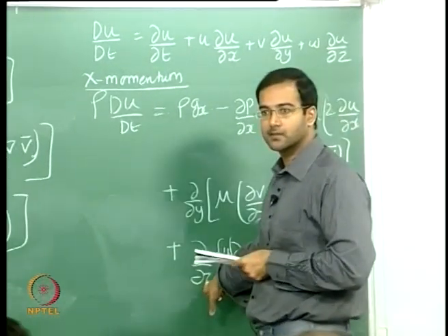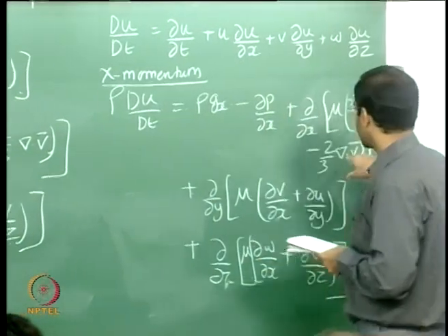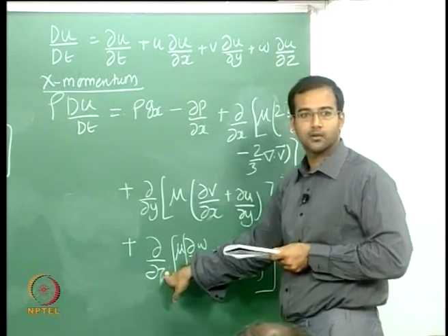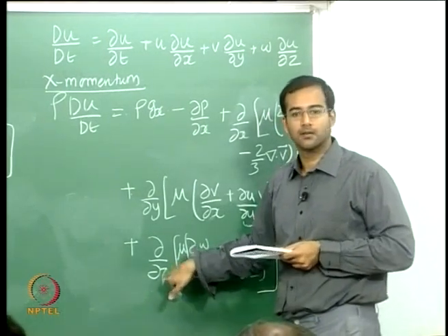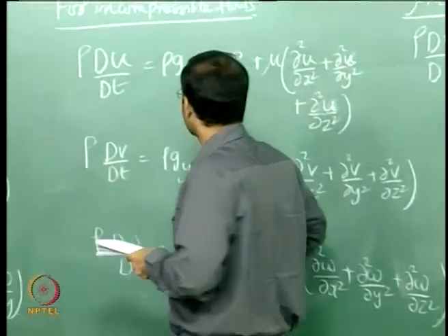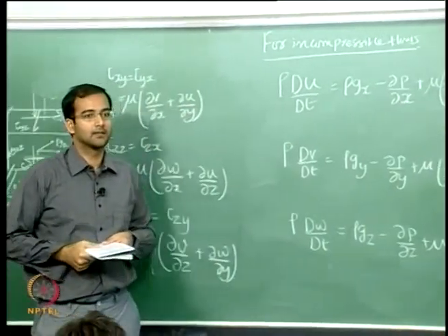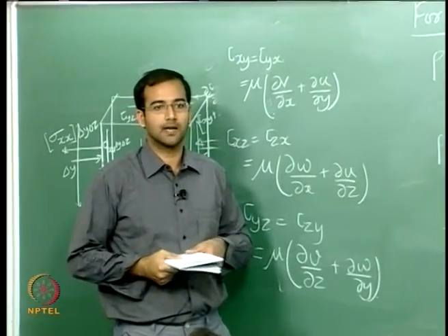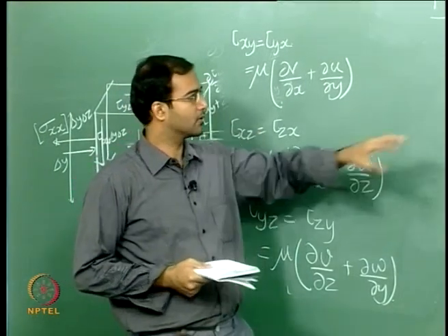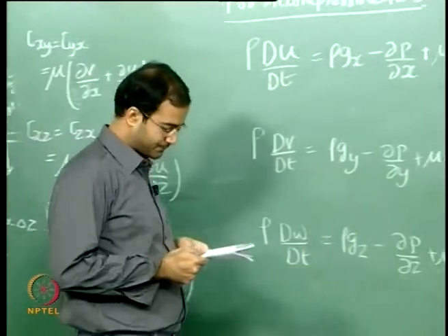So from each of these momentum equations you will satisfy continuity if you group the terms together like that. Okay, so hope all of you got it. The remaining terms will just be the Laplacian operator. So this is the more familiar form, I guess, correct? When you start with the analytical solution of equations, you are more used to this form for incompressible flows.